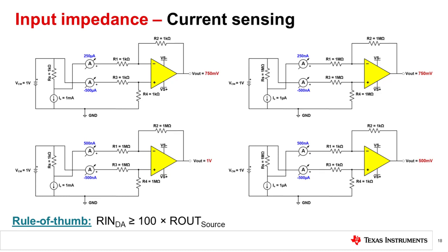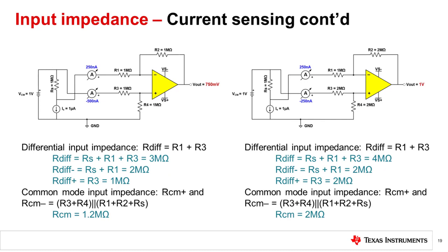When designing circuits, carefully choose your difference amplifier so that the overall system requirements can be met. We recommend that the input impedance of the difference amplifier be 100 times greater than the source's output impedance. In many cases, the source is pre-selected. This means you have no control over its output impedance. You may need to redesign your difference amplifier to accommodate this source.